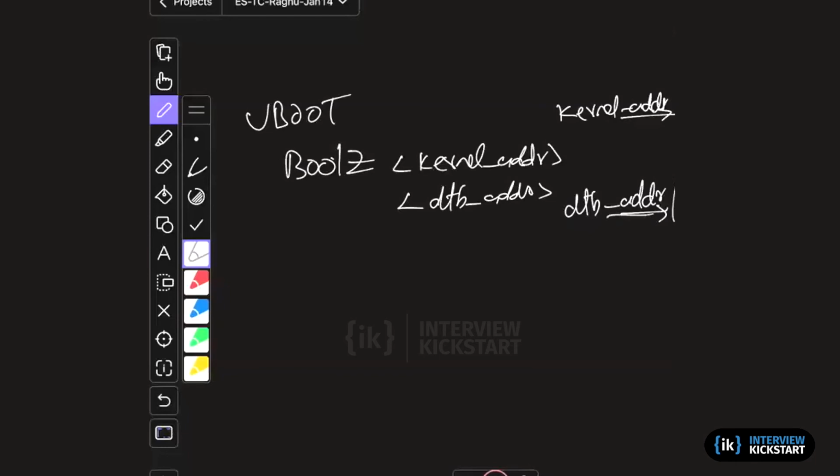In ARM processors, typically this is standardized. A particular register is used in each case. A particular CPU register is used to pass this DTB address. In the case of ARM 32 architectures, it is passed in register 2. So that's done. Basically, you have told the kernel what the device description is in a binary form.